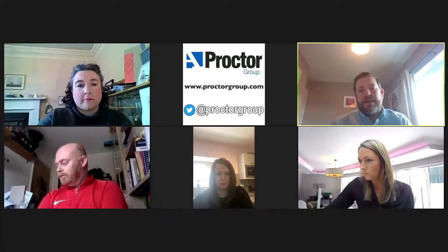So what is your advice when it comes to jointing VOC flex membrane? Is it okay to use tapes? Okay, morning, Tom. Thank you for your question. Quite an interesting one, really. As Proctor's, we really recommend that you weld hydrocarbon membranes. The CIRIA guidance, which is the CIRIA 716, is a little bit woolly when it comes to using tapes as a method of sealing, just for the nature of the restrictions that you have with tapes, such as dusty surfaces.